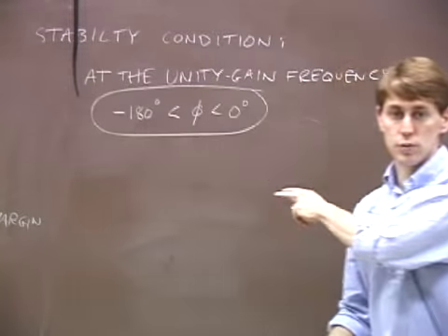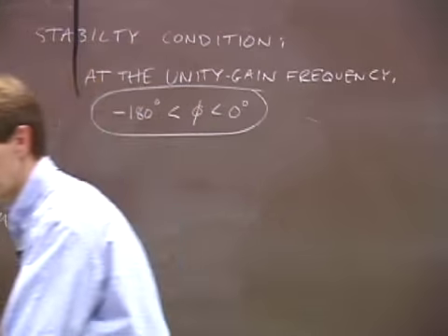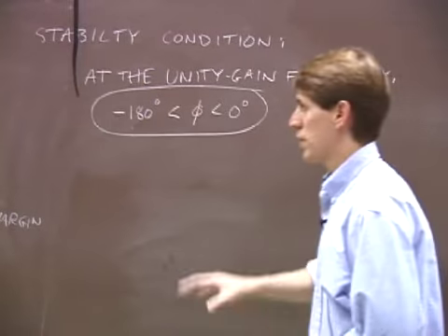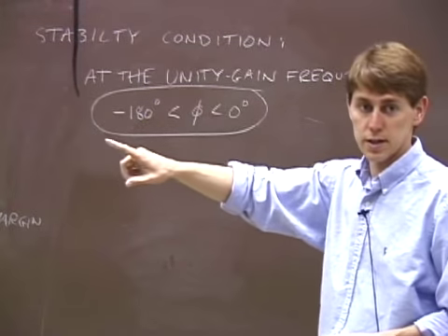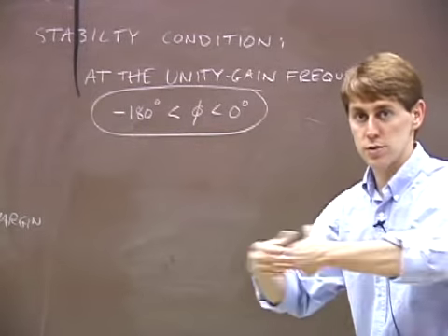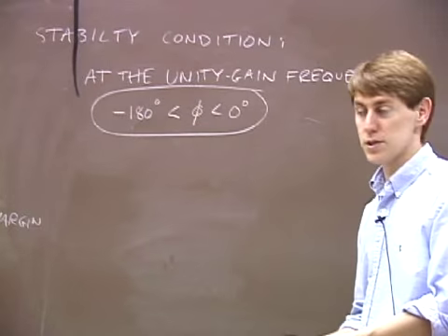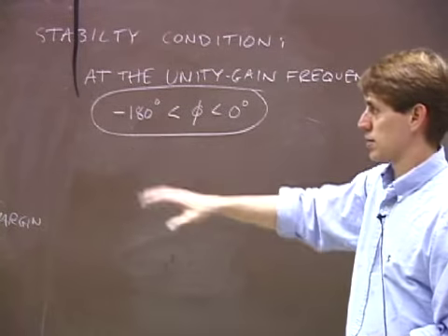And this is the condition that we as experimentalists use when we design these single input, single output control loops. And again, this doesn't contain any more information than what the Nyquist diagram did. It's just a different way of looking at it, and it's the conventional way. When an experimentalist throws up an open loop transfer function or a closed loop transfer function, this is how they plot it. They plot it in terms of a Bode plot.